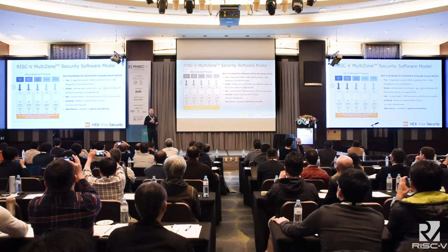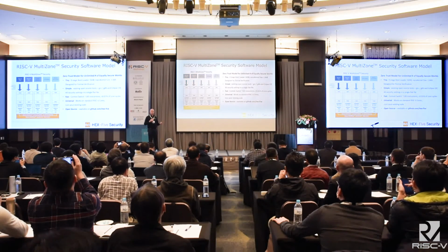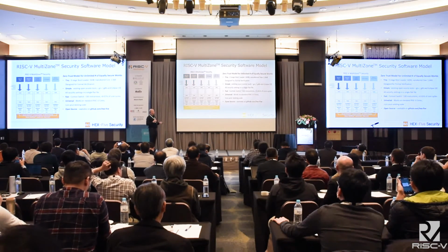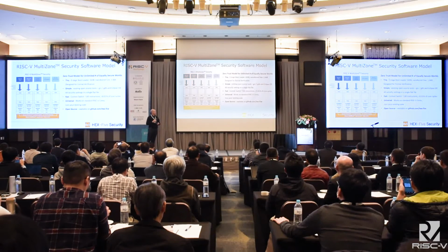The next stage bootloader is about 4 kilobytes. It brings up the system, brings up the nanokernel, and drops it into place. The nanokernel is 1.6 kilobytes in size, and it takes a kilobyte of SRAM.